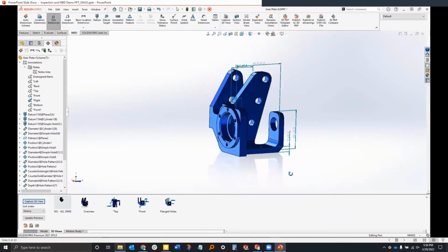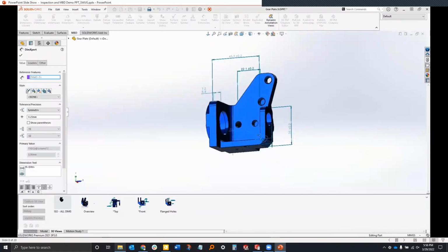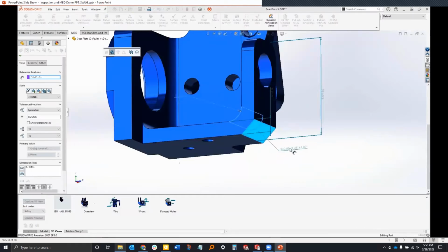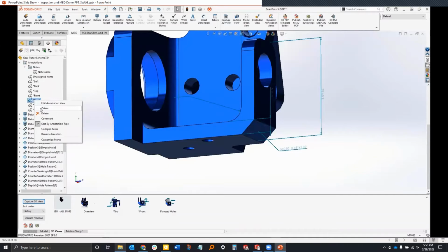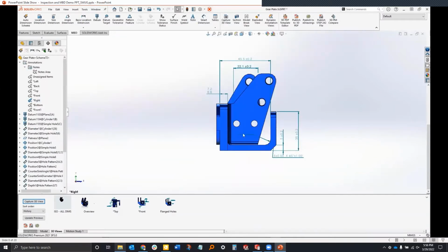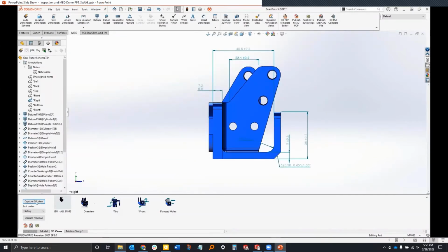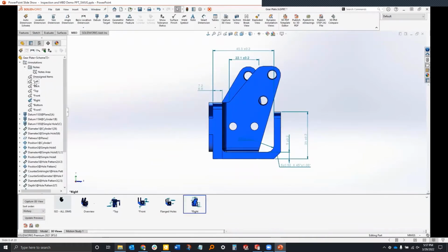I'm going to choose a size dimension. Size dimensions are ideal when we need to have sizes for single items such as maybe a chamfer face or a fillet face. We can see what our end result is starting to look like. Again, I'll set my zoom, which is also captured in that 3D view. And we're ready to go on to our left view.